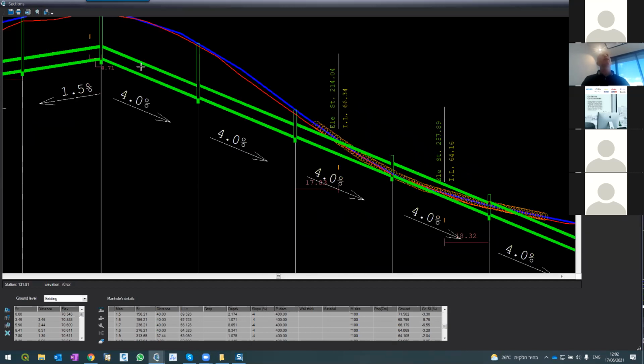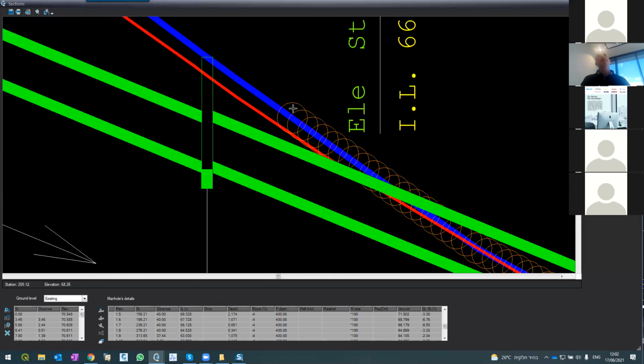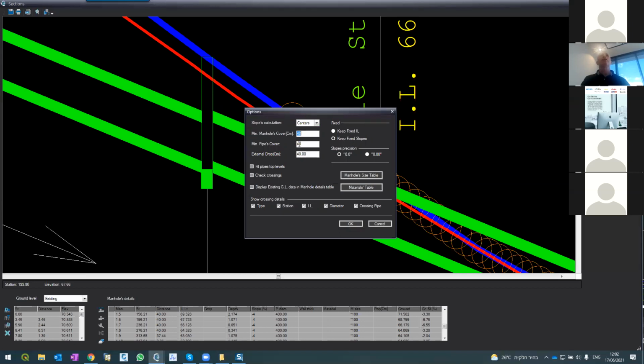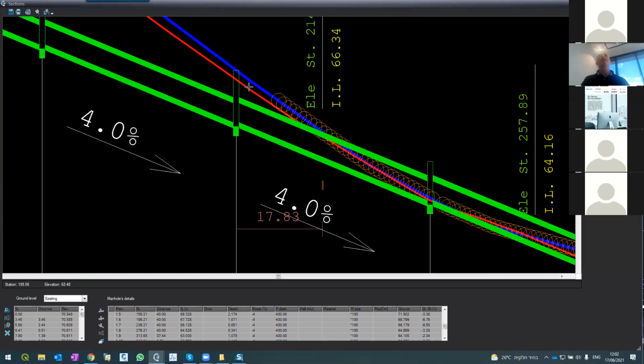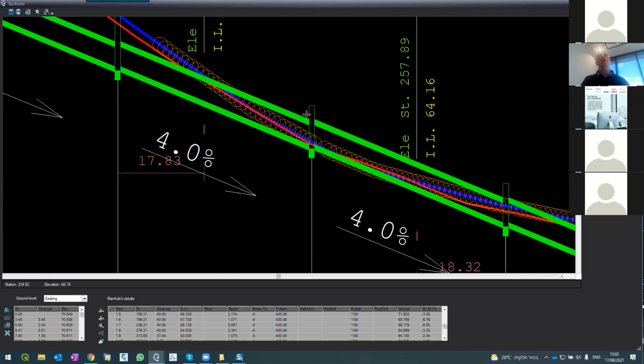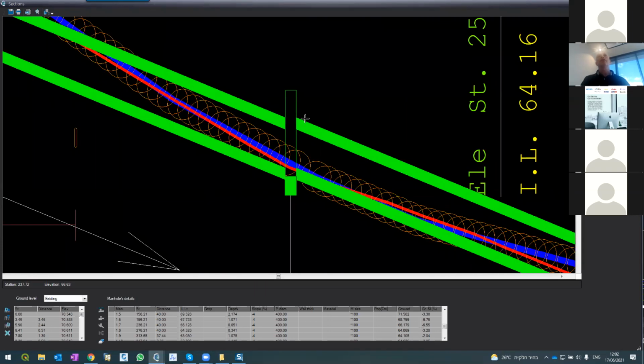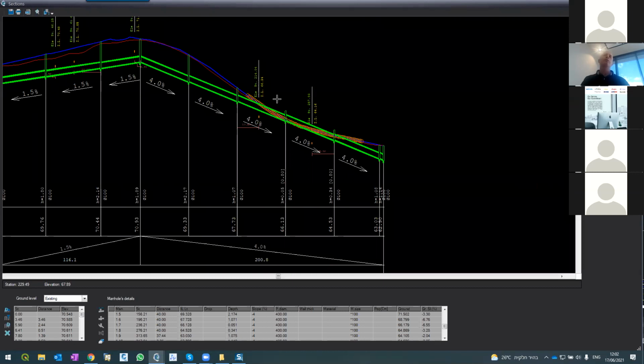I went with 4% and from this point, the software starts alerting that I'm exposing the pipe too much. There is a definition that the system alerts from 40 cm coverage. So here I'm exceeding it, and here actually I'm above the ground. So the system allows me, but alerts. Maybe this is what I want to do, but I don't think so. So I do a drop here.